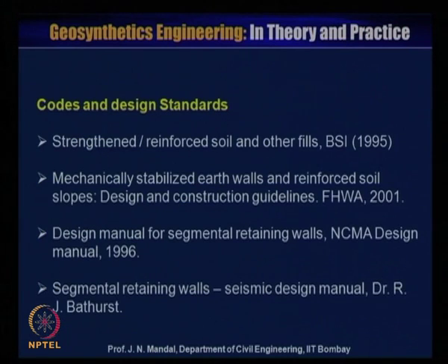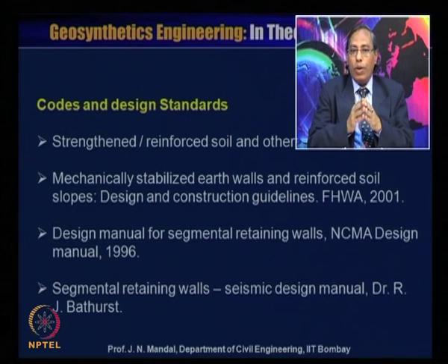You should follow some of the codes and design standards, which we have also followed in this course: strength of reinforced soil walls and other fills, British Standard 1995; mechanically stabilized earth walls and reinforced soil slopes, design and construction guideline, FHWA 2001; design manual for segmental retaining walls, NCMA design manual 1996; and the segmental retaining wall design manual by Dr. R.J. Bathurst.